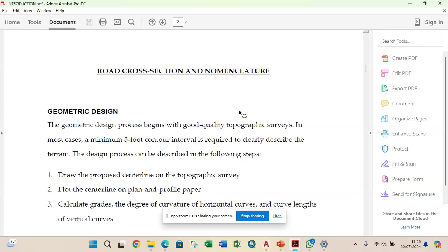What that report will entail is that it's going to cover, one, the hydrological survey or hydrological report, the geographical report of that area, the soil report, and the soil properties located in that area, and if possible the rivers, with all the details incorporated to guide you when you're doing your design.